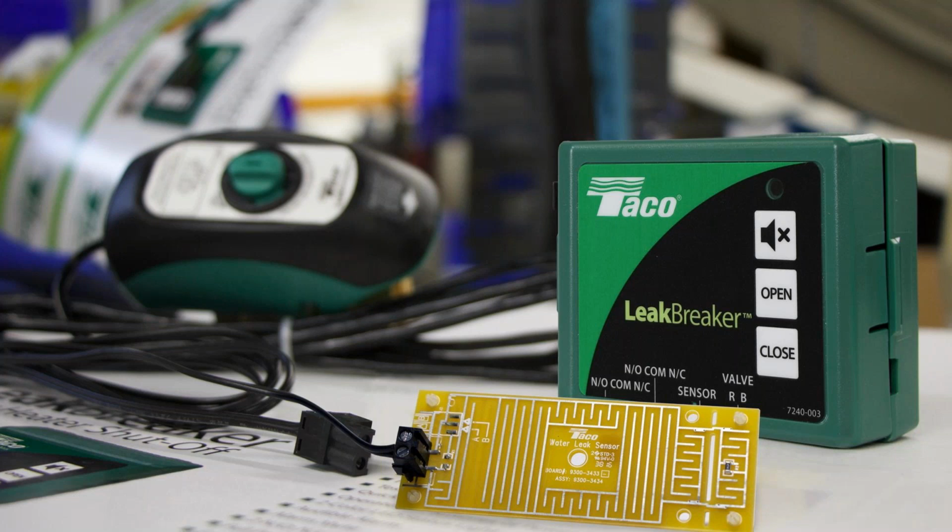When that sensor gets wet, the circuit is completed. As you can see here, these circuits that are printed on this board, as long as it can make a contact going across there, there is water, and this valve instantly closes within about 3 to 4 seconds. You get an audible alarm and a flashing light telling you that the sensor has been tripped and the valve has been shut off. Then you can take a look at the valve manually, and you can see the knob on the top saying it's in the closed position.